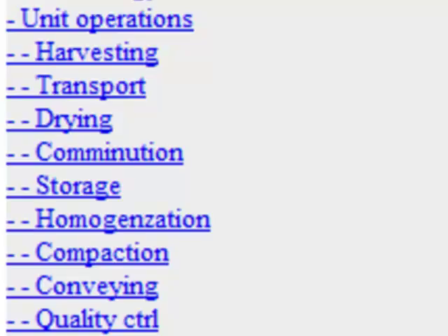Now, the conveying and the dosing of a solid and inhomogeneous material into a reactor, be that reactor a combustor or be it a gasifier or a pyrolyzer, is a problem in itself. And you will realize that the conveying and the dosing is very closely connected to the shape, the ruggedness of the surface, and the density of the particles.